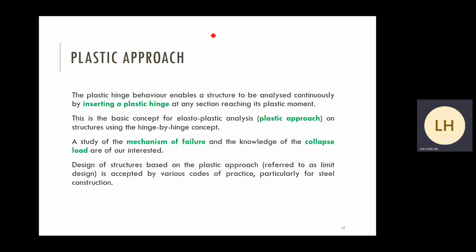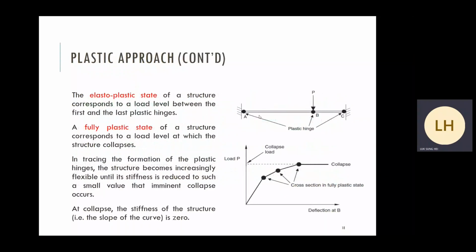But once you understand the plastic collapse mechanism, you can start from the other side. Instead of gradually tracing the behavior of a member, you can directly assign plastic hinges in your structures, in your member, at some critical positions, until the section becomes unstable, reaching the so-called plastic collapse conditions. You can do the analysis in this way, without tracing the behavior in detail. We can directly assign plastic hinges